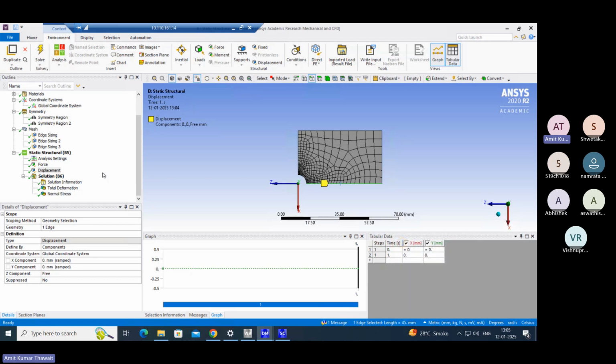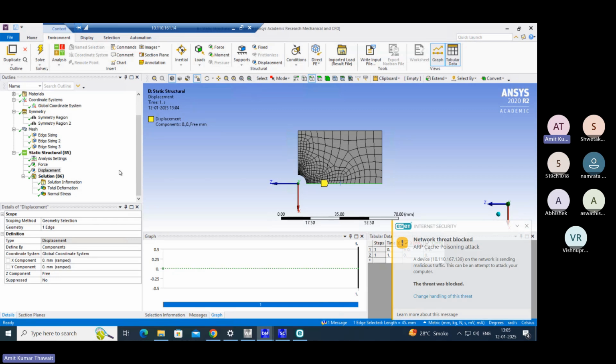But when you select that remote displacement which we used earlier, you will also have three rotation options. So here we can select anything. Since there is no rotation, we can assign them 0, or directly select displacement. But in the previous beam problem, we needed rotations also because of the hinge location and the rolling supports. So rotation was important there for the beam problem. Here rotation is not important.